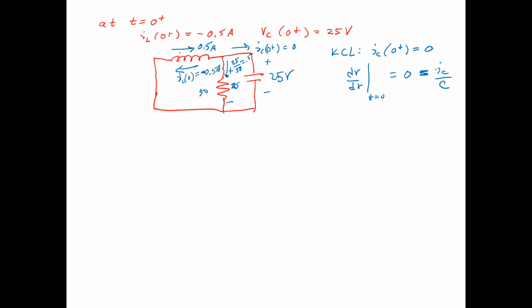So now it's the derivative that's 0. This is actually a good thing. I'll plot it in Wolfram Alpha again when we get the solution, and you'll see that you can combine these things in such a way that the initial derivative is 0, not the initial value. So here's v of t. Our solution is A1 e to the minus 854t plus A2 e to the minus 164t. And our v of 0 is just going to equal A1 plus A2, which is going to equal 25.